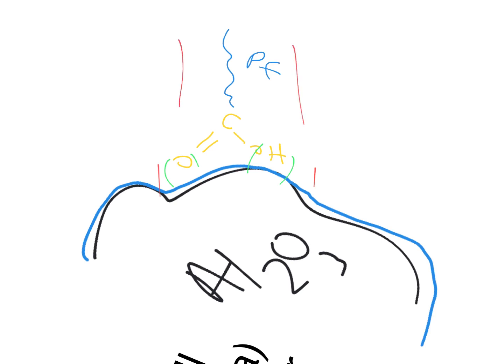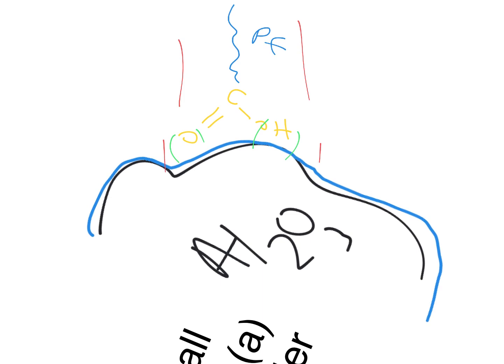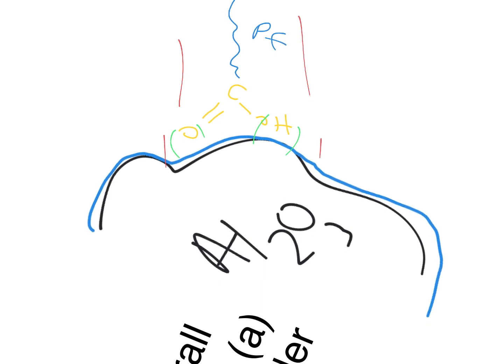All right? And this is where the tail that comes off the surface of those particles comes in. Those tails come off the surface, and they get in the way of the particles getting close to each other. Okay? And so this is where these are processing aids. We talk about, like I said, oleic and stearic. Those are processing additives, and this is all that they do. And this is a very trivial layer. This is not something you can turn around and put into a melt by itself. It needs to have a lot of other polymers around it. But that thin layer sitting on top of these ceramic particles plays a huge role in the success or failure of the overall process. Okay, how's this going to go?